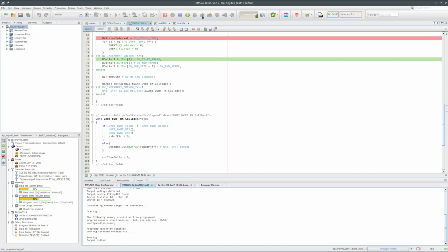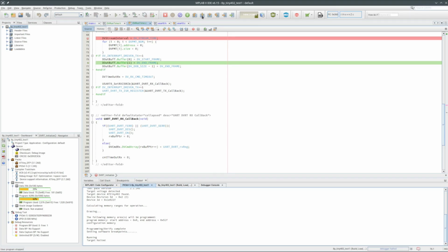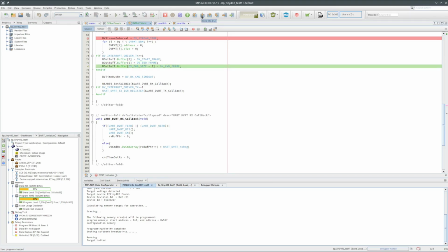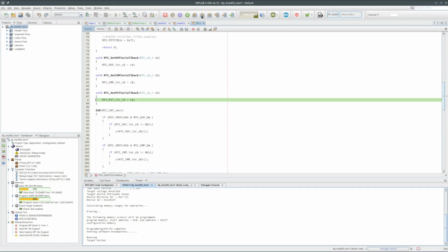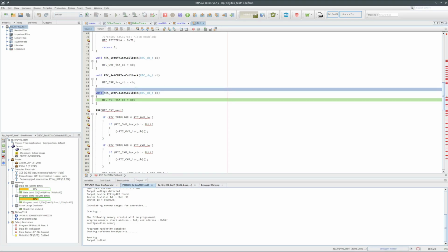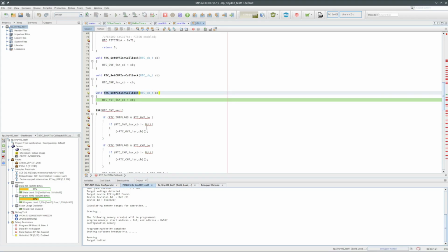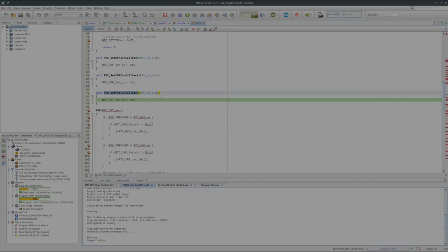In looking over the transmit callback, I know I'm going to have to make some changes. But this was a very unexpected problem. Here I'm stepping through the DVRT initialize routine, and this line should set the callback for the RX interrupt service routine. At least I thought it should. But when I follow this code, it's setting the callback for the periodic interrupt timer. I did this a couple of times. I'm still not sure what is going on here. But after this, I decided to forego all the ISR callbacks and just put the ISR code where needed.